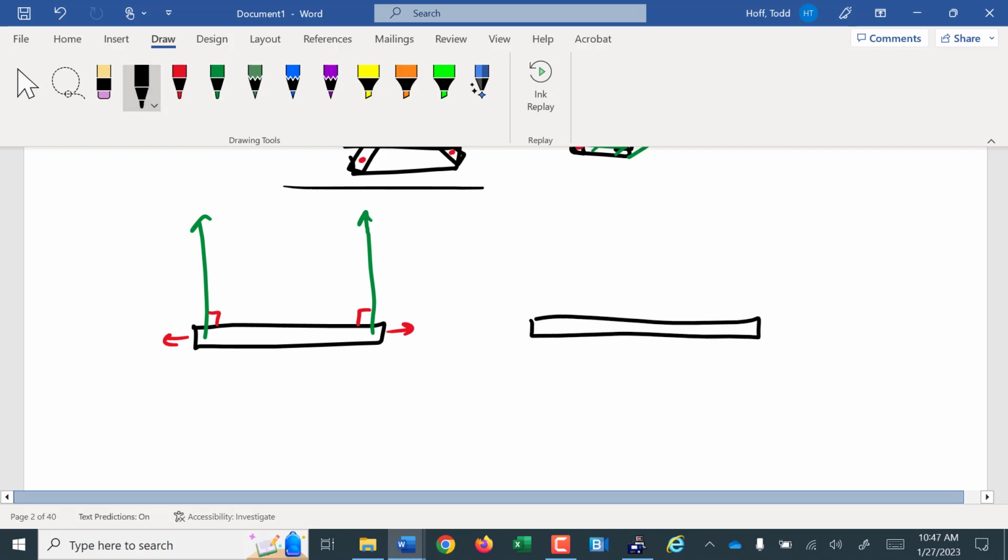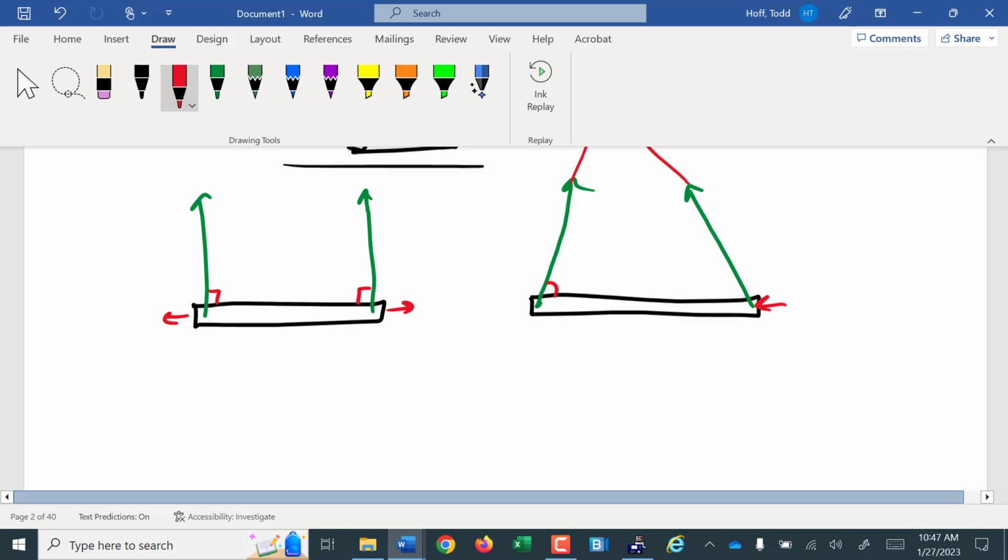So most of the time, when you set up a sling, you actually have those ropes or chains slightly angled inward. When they're angled like that, if you try to push this to the side or make it swing, it's not going to do it nearly as easily because the tension on those is holding it in, keeping it from swinging. Because these angles, if we're extending it, would form a triangle, and it makes a rigid shape, or a more rigid shape.